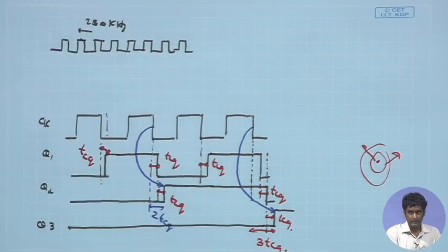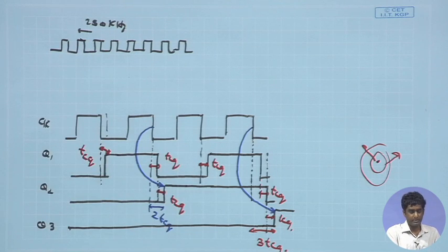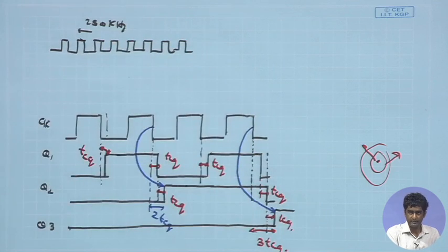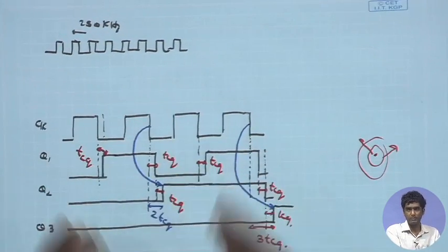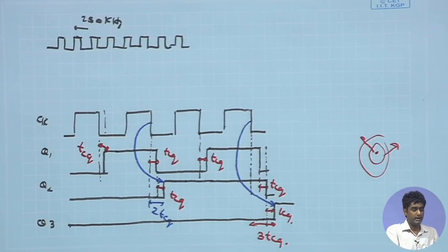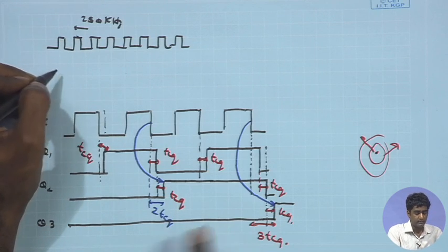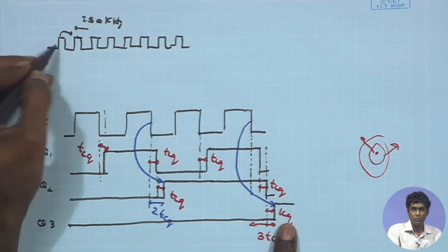We are having around 2 kilohertz sampling rate, and therefore, within 0.5 millisecond we want around 127 pulses of the clock, so that we can count 127 levels, and therefore, we arrive at this 250 kilohertz requirement for the clock, and we would therefore like that the ripple should be through within one clock period.